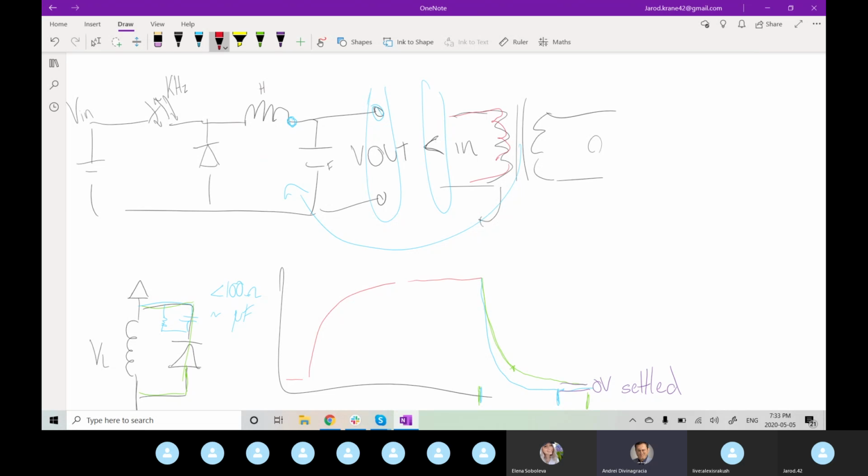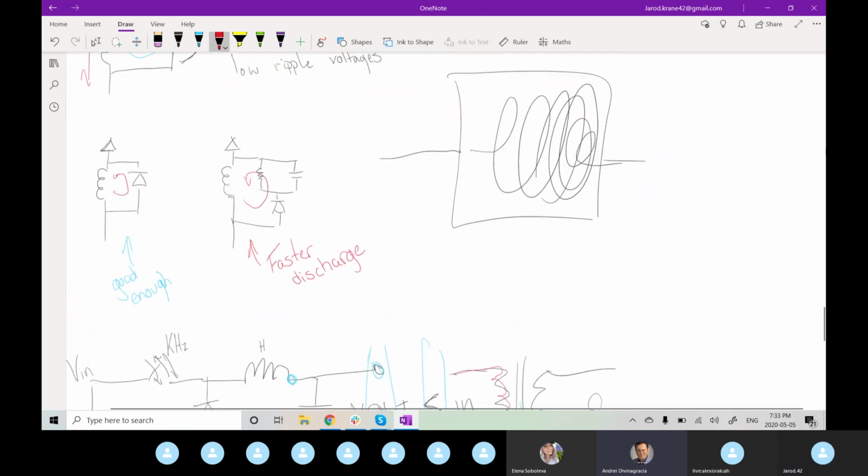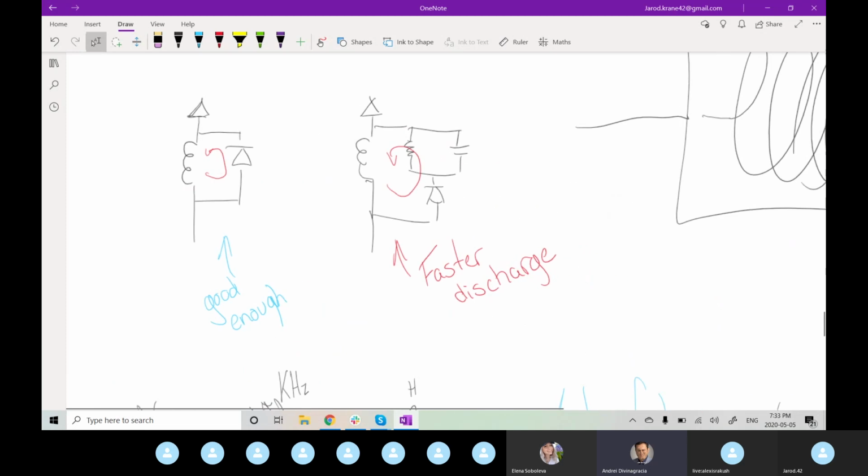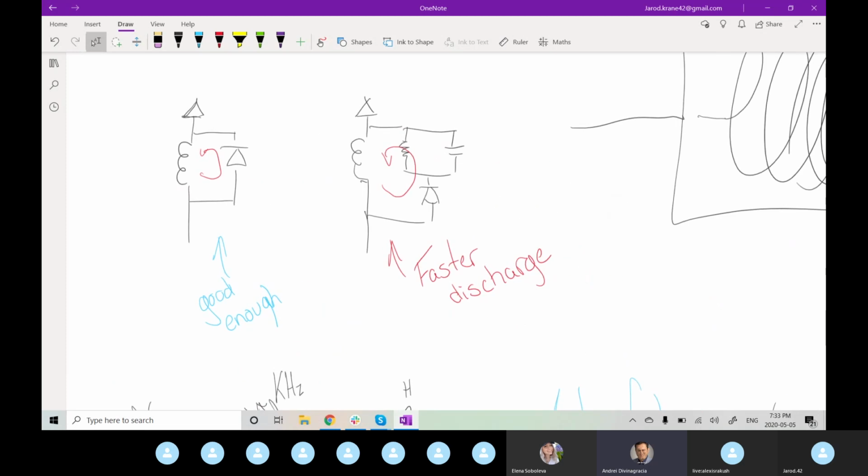Sorry, another thing actually. When you say high speed switching, the snubber with the resistor and the cap is designed so you're dissipating power a lot faster. When you're switching the inductor on and off really fast, like a PWM motion, wouldn't you want the faster discharge?